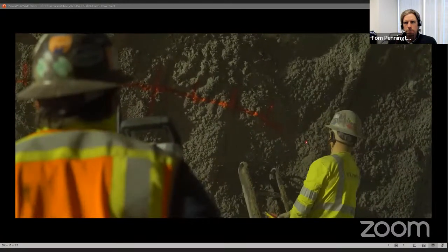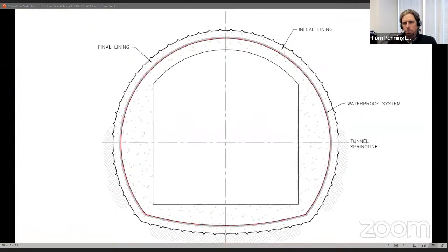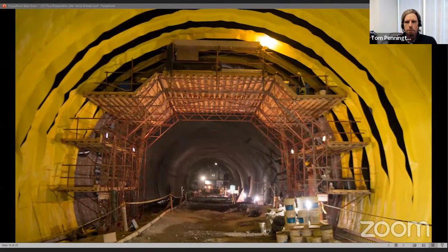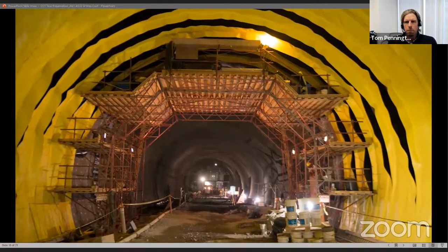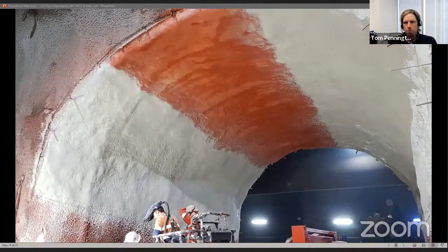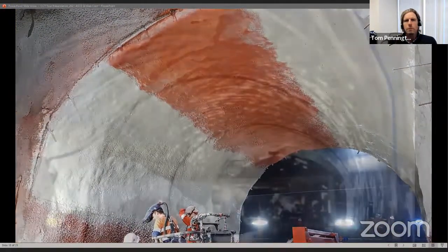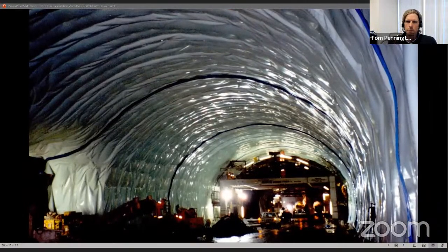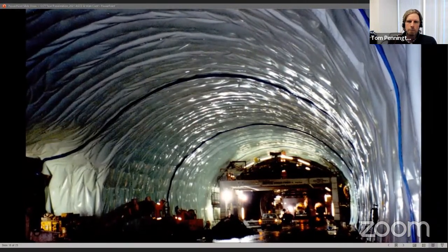After the tunnel is excavated, a waterproofing membrane and a permanent cast-in-place concrete lining is installed to prevent water seepage into the final structure and to carry long-term ground loads acting on the tunnel. The permanent concrete lining also provides a smooth and flat walkway, walls, and ceiling and allows the tunnel to be fit out with utilities including power, lights, plumbing, ventilation, and electronic communication and security systems.